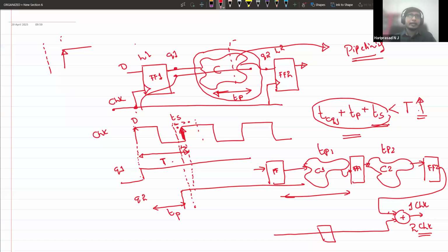And it doesn't mean that as soon as you latch here, you can remove the input. So the data shouldn't go low here, right? You have to hold this data for some time after the clock edge. Okay, so this is the time for setting up, that is why setup. After this, we have to hold the data so that your output will be stable after the clock edge, right? So this is also very important.